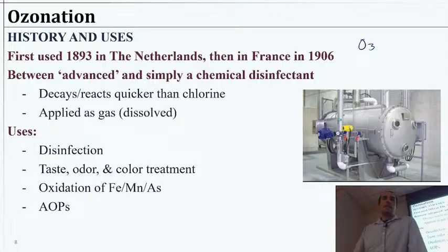Okay, it typically decays by reaction with water or other stuff a good bit quicker than chlorine would decay, but it's not like instant. So it'll hang out a little while. So we'll often apply it as a gas to water, meaning we're going to have some sort of an aerated type of situation, but it's ozone that we're bubbling through. We'll use it for disinfection sometimes. It's pretty good against cryptosporidium compared to chlorine. The cysts are just simply not as resistant to it.